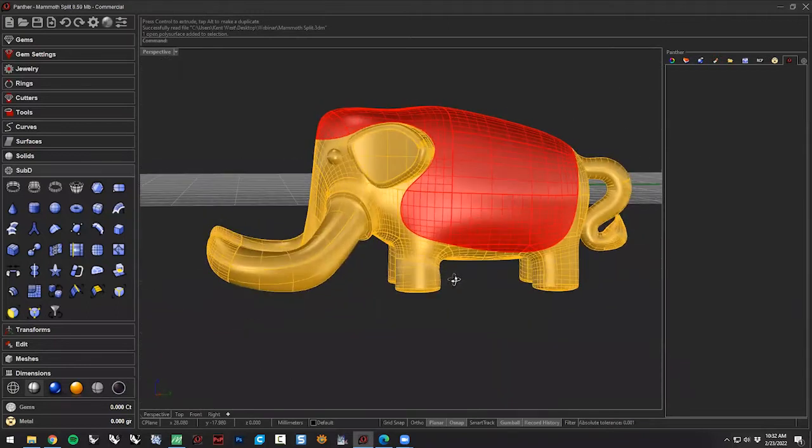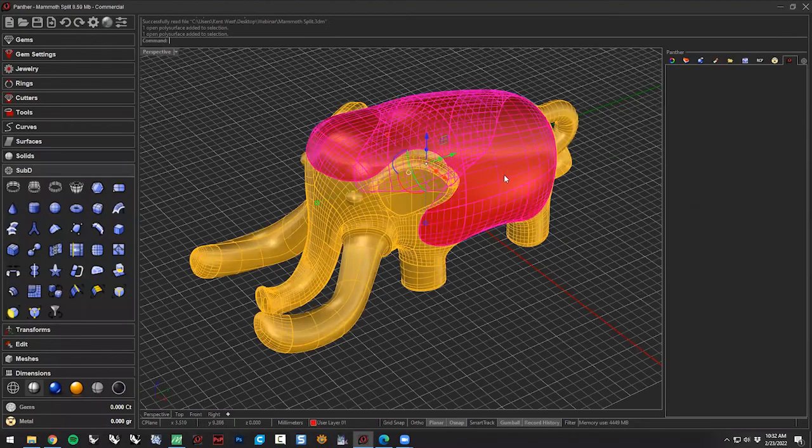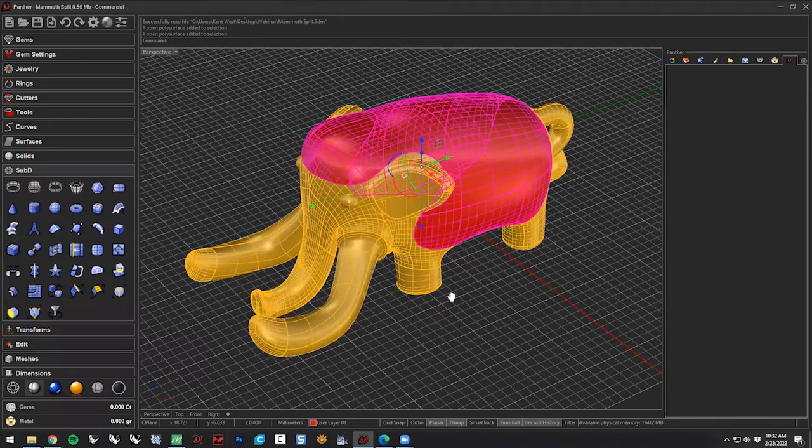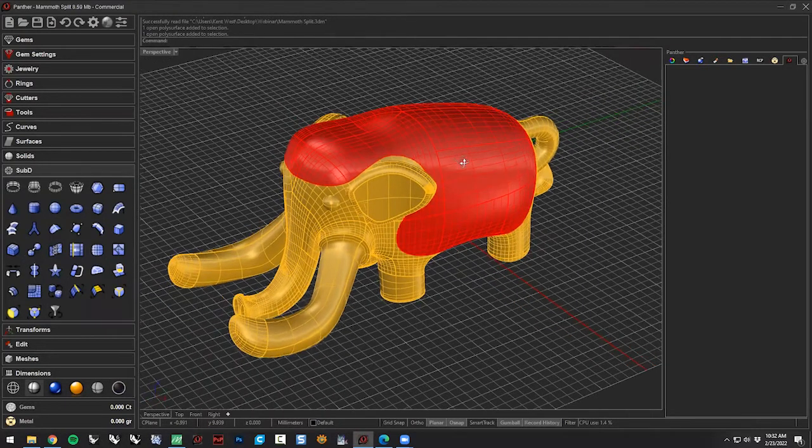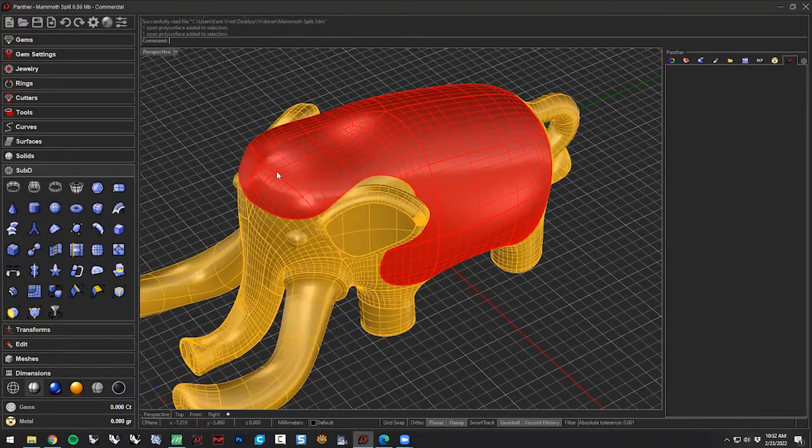And then what I did is I drew a line right along here, and then around and up, and I projected that onto the surface and split it. Now, I'm going to use Panther's Pave builder, which is very powerful and works really well. But I can tell you, having used it, that it's not a big fan of having a surface that is made up of a bunch of subsurfaces that we see here. So this is a big poly surface, and I would like this to be much more predictable. So I want to make it one surface.